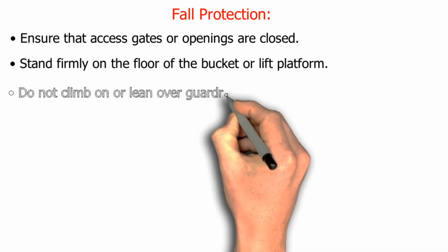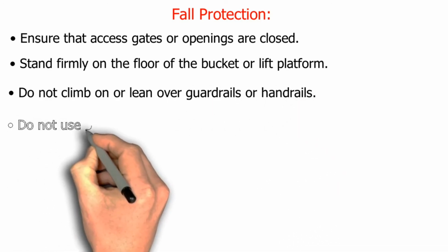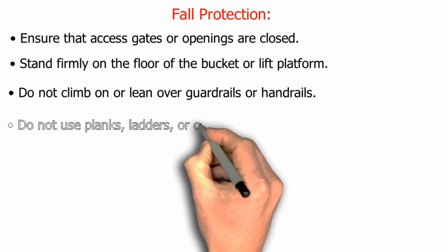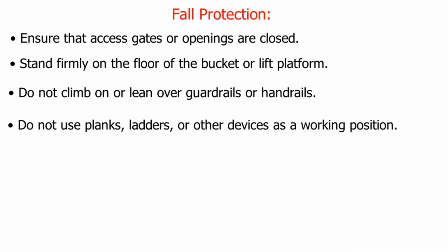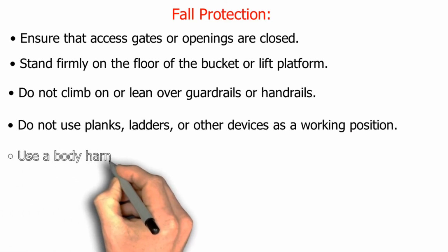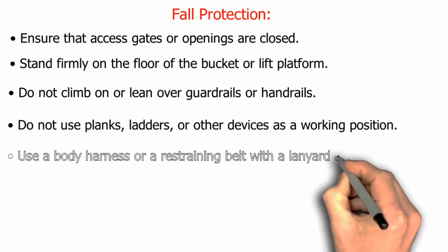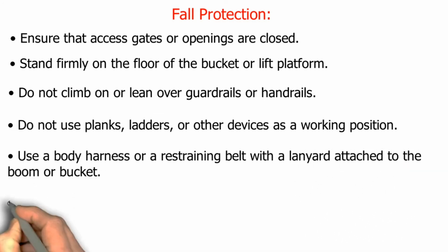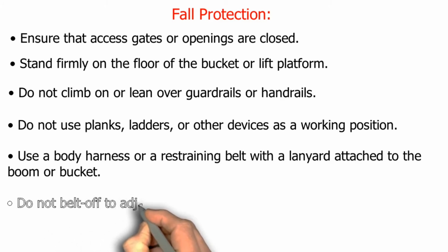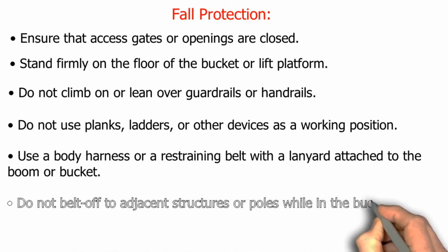Do not climb on or lean over guardrails or handrails. Do not use planks, ladders, or other devices as a working position. Use a body harness or a restraining belt with a lanyard attached to the boom or bucket. Do not belt off to adjacent structures or poles while in the bucket.